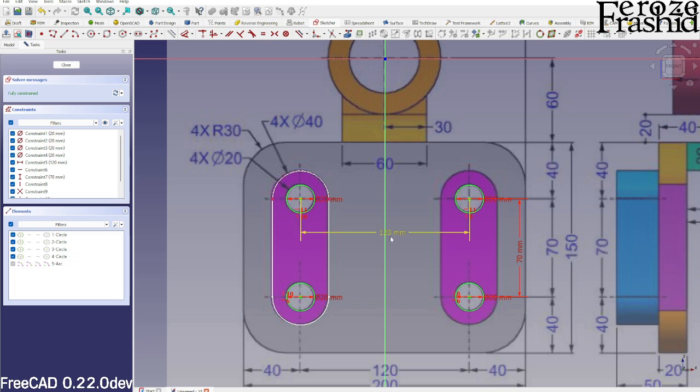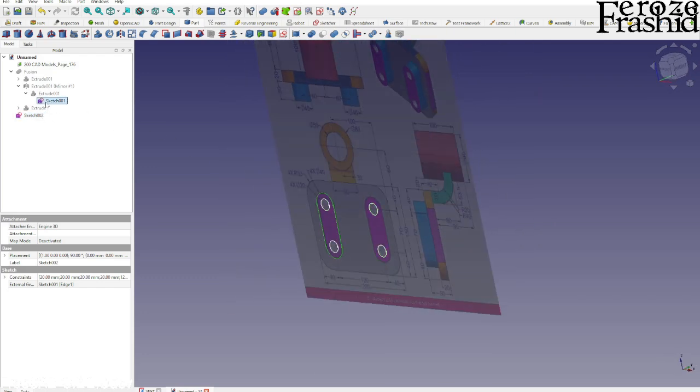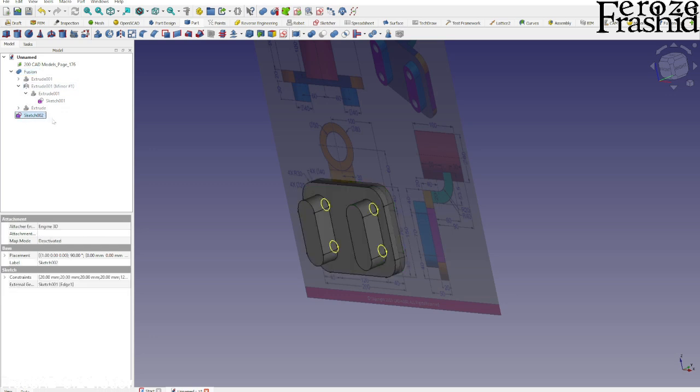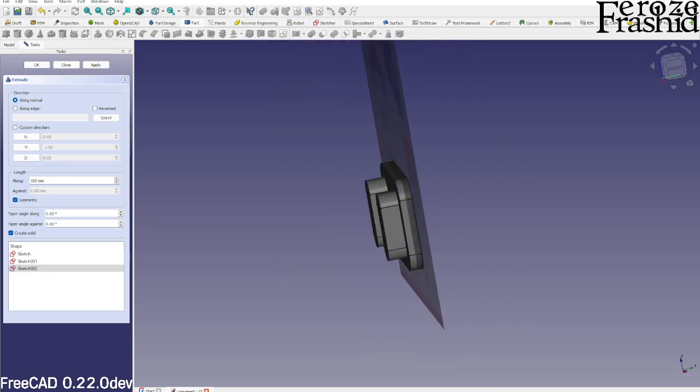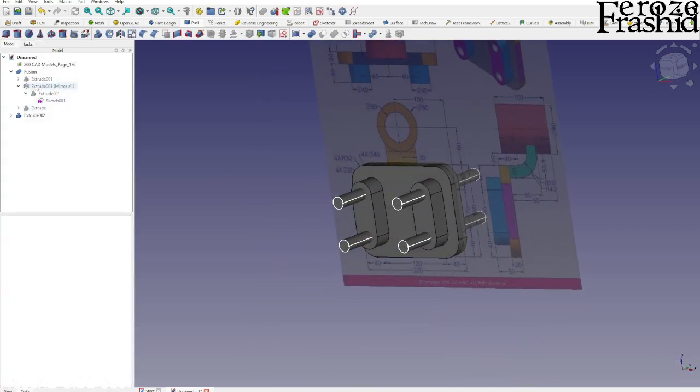All right, so we have our sketch, new experience, but there it is. That's our 4 holes. Let's bring back our fusion, and now I want to extrude this as much as I need, maybe more than what I need. So I'll say 100 in symmetric way. Not enough. Maybe 200. All right, so it crosses through. Now I can make a cut.